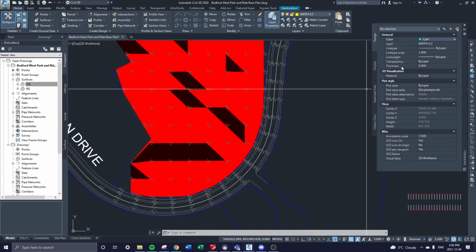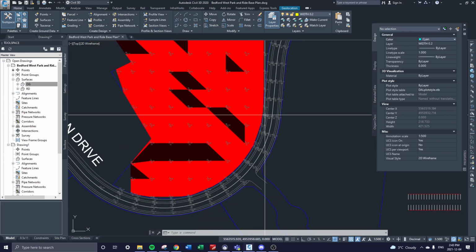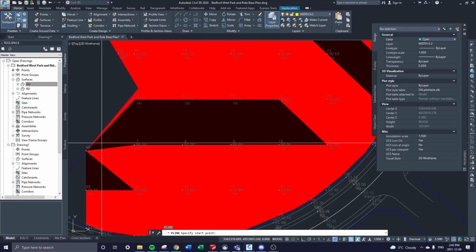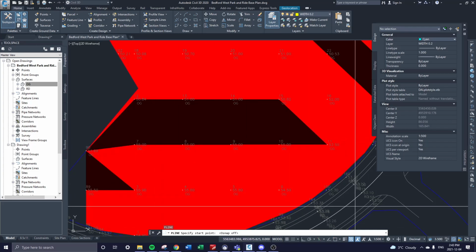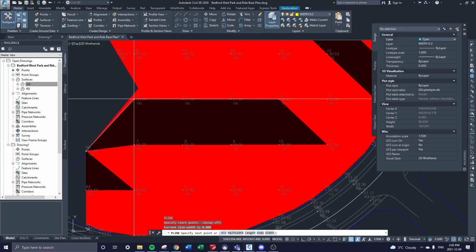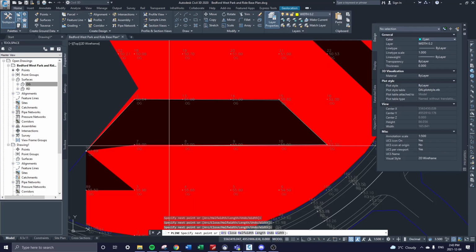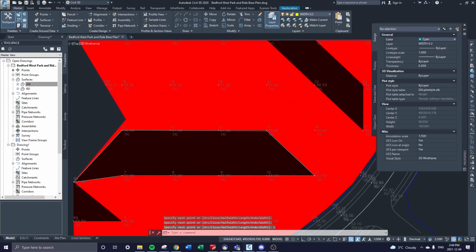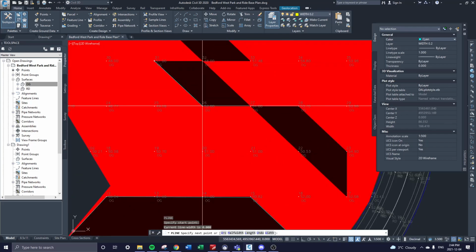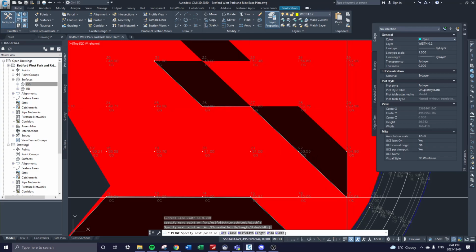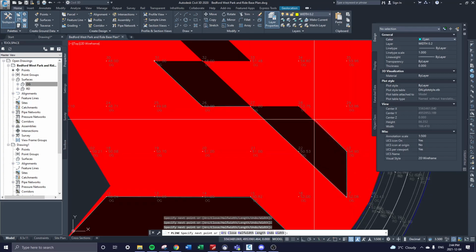And we're going to make the areas in this cyan color. You might benefit by turning your snap off for this. If it's picking points that you don't want, you might have issues. And just use polylines to kind of trace around the areas that are greater than 20% slope. You know, it's just connecting the dots.